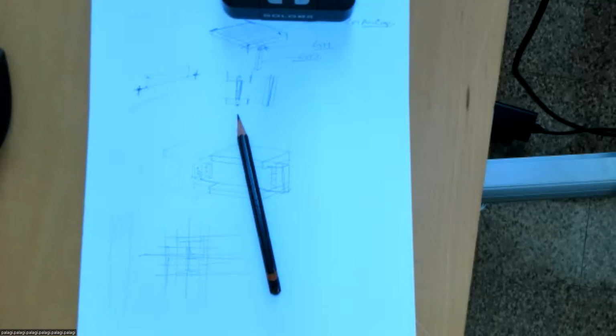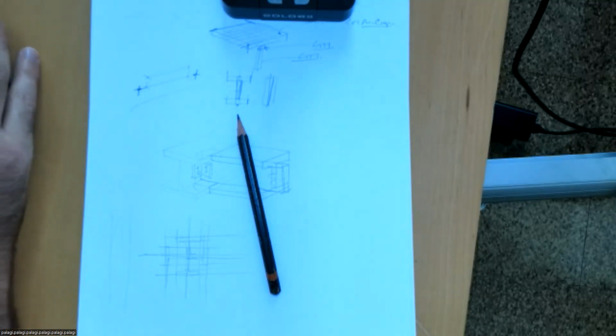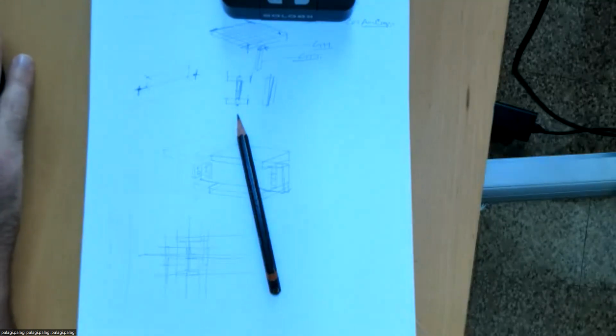In essence, by naming something, you can control it later. If I don't name it, then it just exists the way it is. Sometimes they like to use a little different terminology, but it's all just making it a parameter that you can change later. So the same way, I'll grab this one and say I want it to be the metal thickness. So I can just go metal thickness.